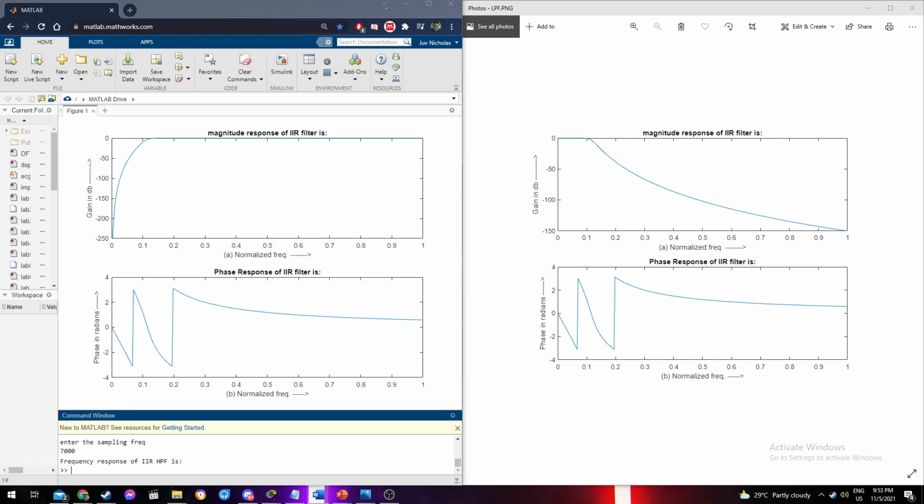Digital filters with infinite impulse response are fundamentally different from FIR filters in that they constantly require feedback. Each IIR filter output sample is dependent on both previous input samples and previous filter output samples, unlike FIR filter output samples, which are solely dependent on past input samples.